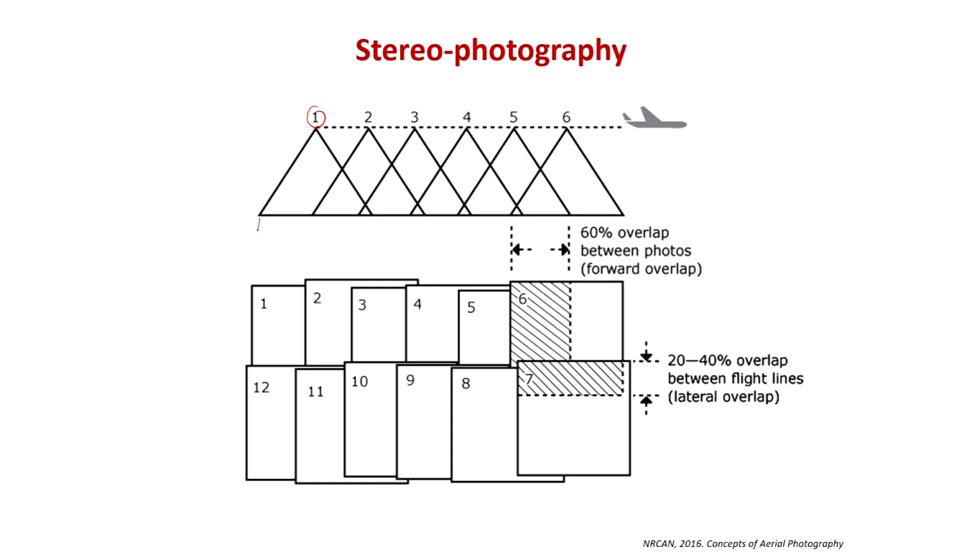So you are having this photograph over here, and this is your overlap with another photograph. If you take this as a center here, and this as the center here, this will be an overlap of 60%, and this will have the overlap of 60% over here. Okay.